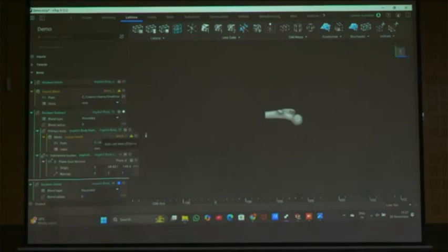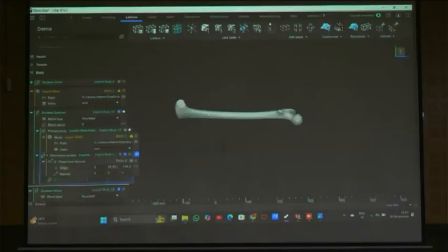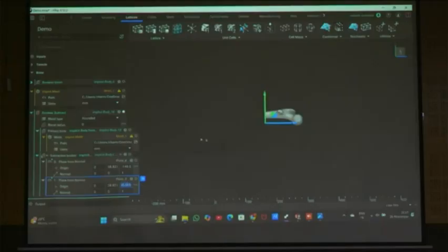So one more plane I will take. This is the implicit body, right? See, this is removed, and I need to remove from this side also, right? So one more plane we will take, plane from normal, or otherwise I will copy the same plane. Control C, Control V, and this symbol is there, right? That is the toggle visibility. So this plane I will drag here.